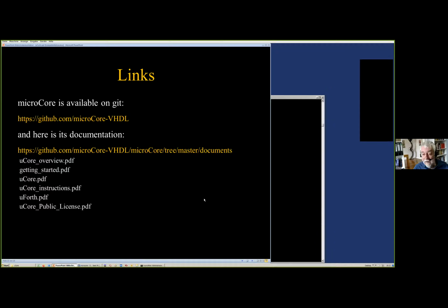Well, the nice thing about it is it just contains the FPGA and the voltage regulators for 3.3 volt and 2.5 volt. The 2.5 volt is if you use it for LVDS. And it has an RS-232 converter on it, and that's it. And besides that, it has lots of unused pins which can be routed to headers, and you can stick on other boards that do specific things.